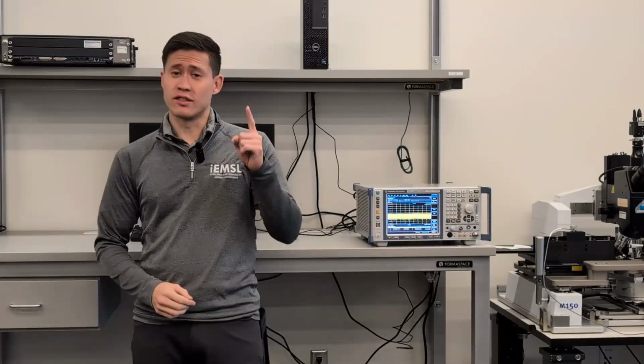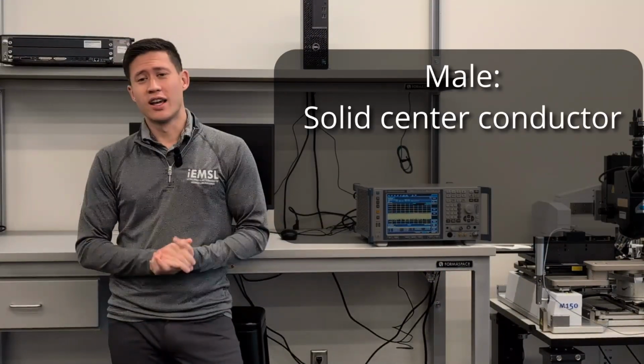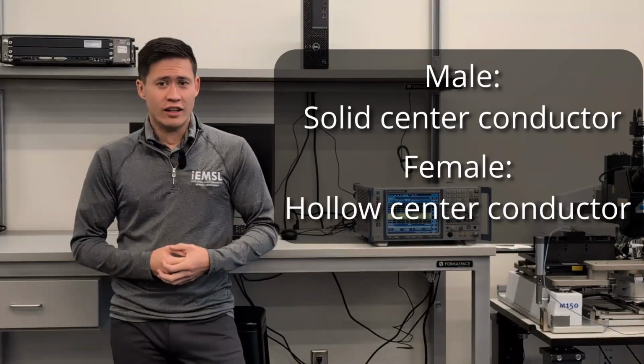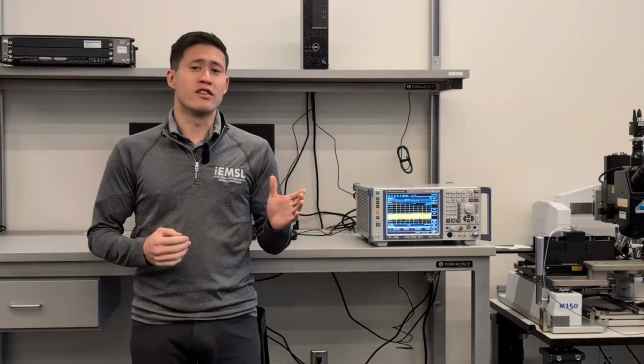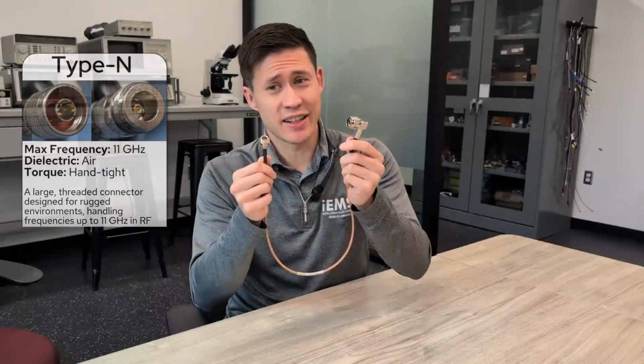All you have to do is look at the center conductor. If the center conductor is solid or looks like a pin, that means it's male. And if the center conductor is hollow, then the connector's female. The key takeaway is that regardless of the overall shape of the connector, the center conductor is what determines whether it's male or female. For example, this is a male and this is a female type N connector.